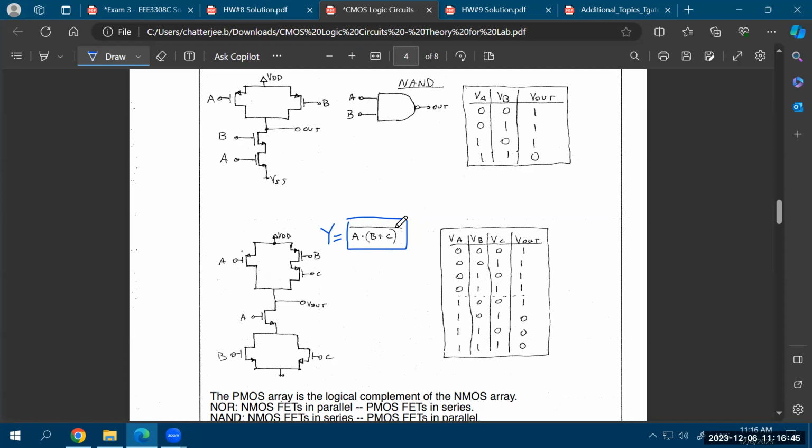So functionally, that is a correct solution, yes. If you just represent this function as a combination of NAND gates and NOR gates, and then draw those NAND gates and NOR gates accordingly, and draw the internal circuits of the NAND gates and NOR gates, it's functionally a correct solution. But you'll see that you'll be using so many transistors in that case that it will not remain an efficient solution. Of course, you might get full credit for that. But for example, here, let's say this was the function, and we saw the implementation like this in the class. And how do you implement this?